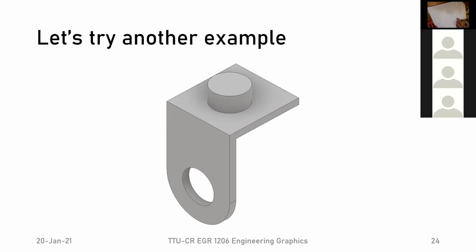Now, there's two more center lines that we have to do. And those are the center lines for our hidden lines, right? Remember that these two hidden lines here were the edge of the circle. We have this circle here with a hole, so we have to tell people that this is not a rectangular hole somewhere, but this is a circle, right? So we have to do a center line to that cylinder as well, right? It's the same type of cylinder here.